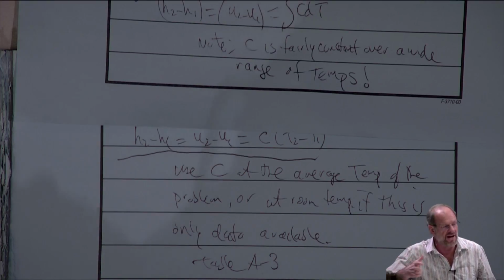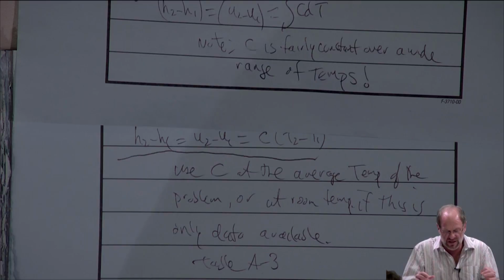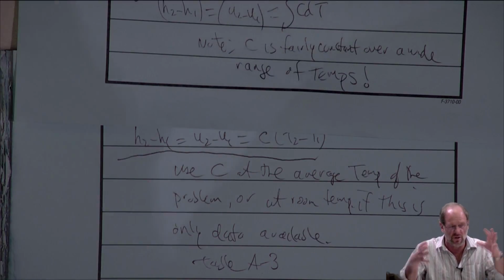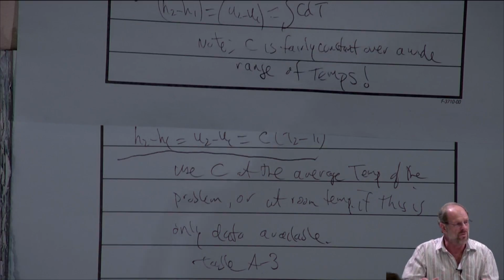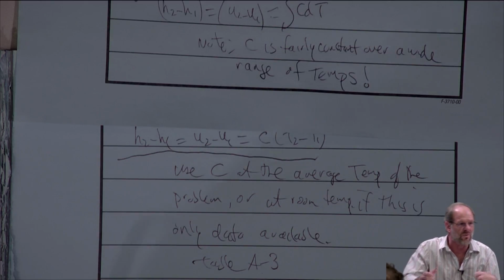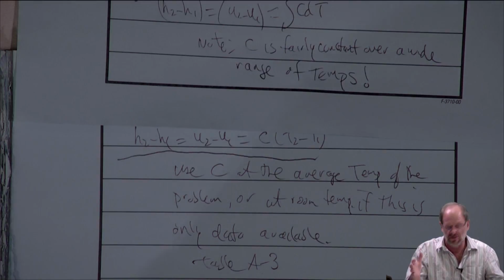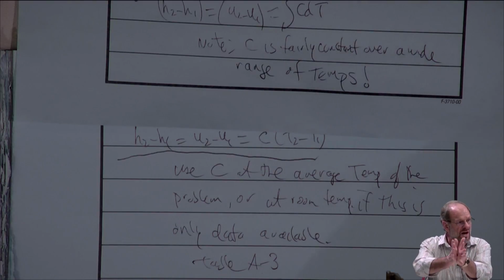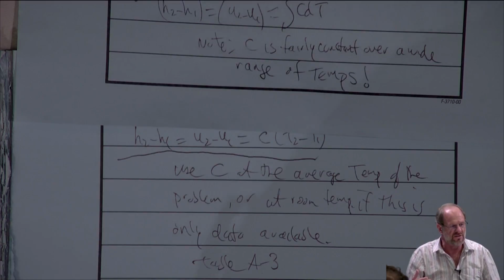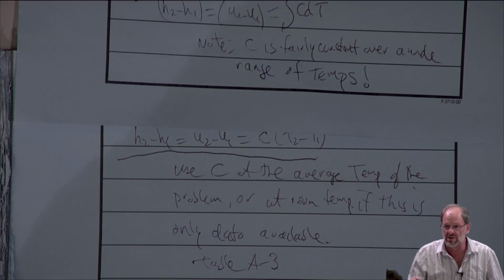So for instance, if you have iron and you heat it up until it's a really high temperature, almost liquid or high temperature solid, glowing bright orange, and you drop it into water, that iron is going to cool at a particular rate. If you drop it into some sort of an oil, it's going to cool at a different rate. If you let the thing just sit there in the atmosphere, it's going to cool at another rate. And depending upon how you work this iron, you can roll it when it's cold, you can roll it when it's hot, basically applying pressure. But all these are going to give you different physical properties for that material. So this is a quenching problem.